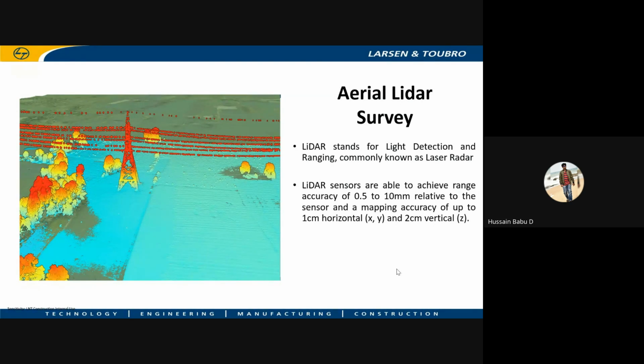So by post processing technologies in the lidar survey, we will remove these external factors, and we will develop one DEM, the digital terrain model, which will have the elevations of only the terrain details, which should be used for our engineering purpose. And all these surface models will also be used for some intervisibility analysis for OMS. As OMS have the radar communication system, we need intervisibility between two OMS to communicate with each other, so that we can assign which outlet system can be opened at a time.